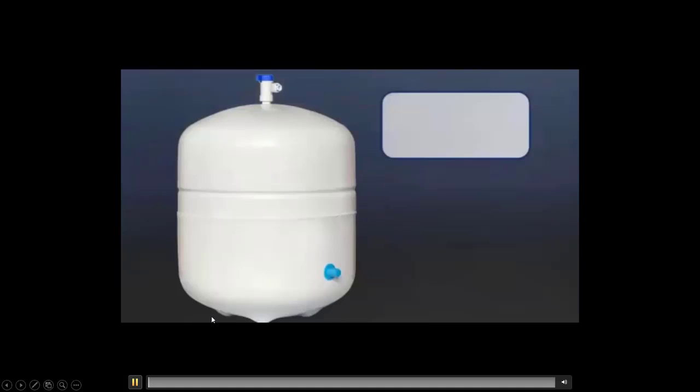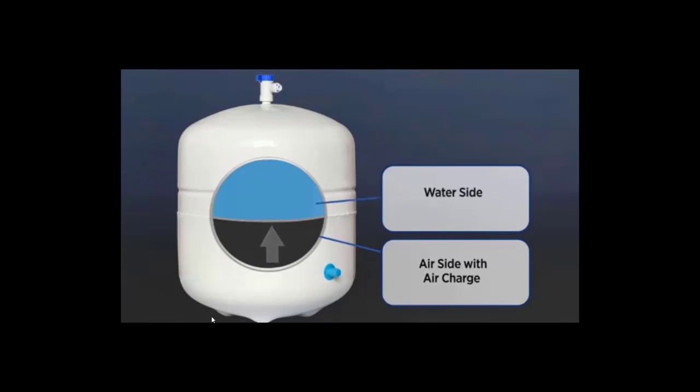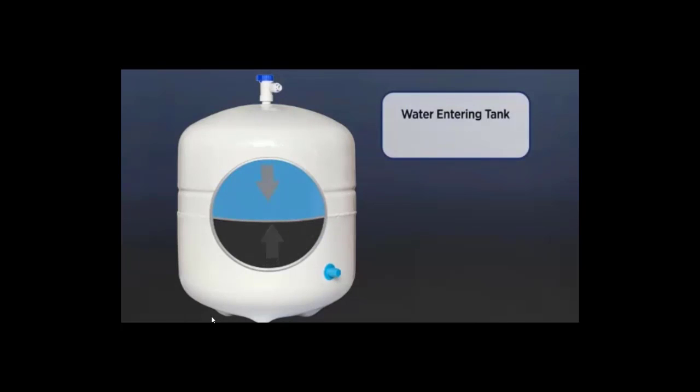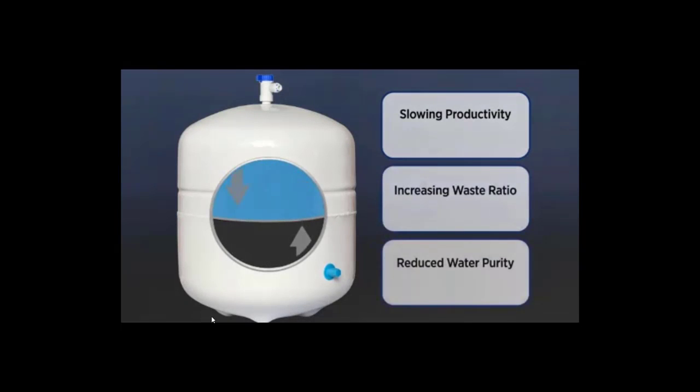Let's look at this one more time. The issue with membrane production slowing down due to the storage tank back pressure is that the wastewater, or concentrate, flowing down the drain is not slowing down. The slowing of the production flow rate does not in turn slow the wastewater flow rate. This means that the ratio of the recovery and the reject will increase, and increase a lot, I may add.